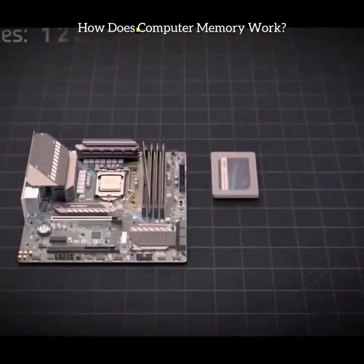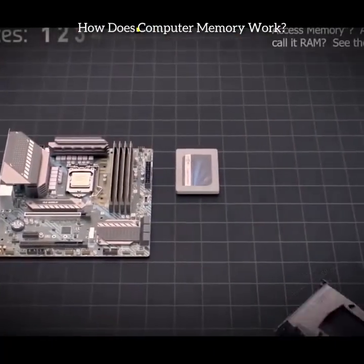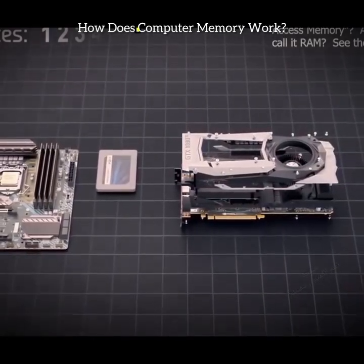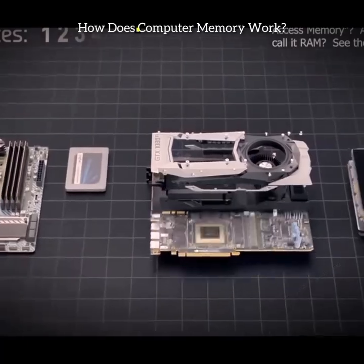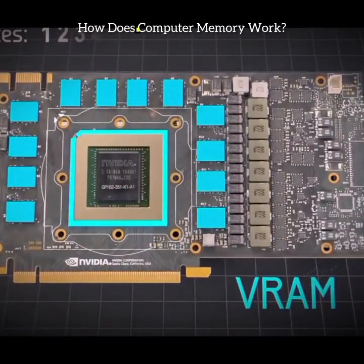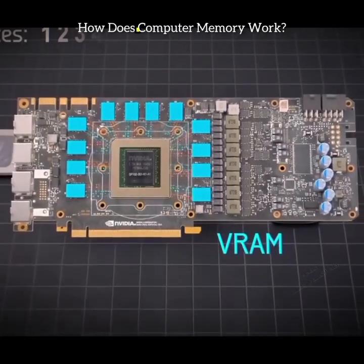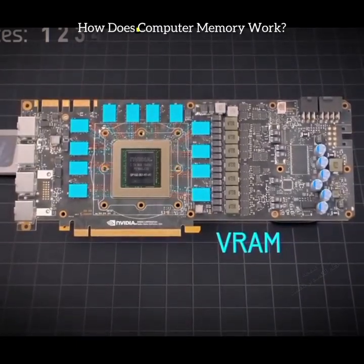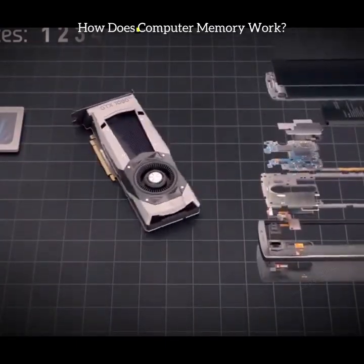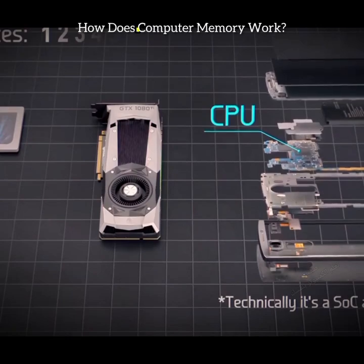A few quick notes. First, you can find similar DRAM chips inside GPUs, smartphones, and many other devices, but with different optimizations. As examples, GPU DRAM, or VRAM, located all around the GPU chip, has a larger bandwidth and can read and write simultaneously, but operates at a lower frequency. And DRAM in your smartphone is stacked on top of the CPU and is optimized for smaller packaging and lower power consumption.